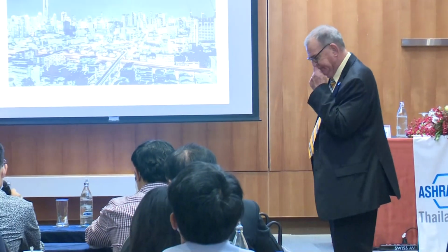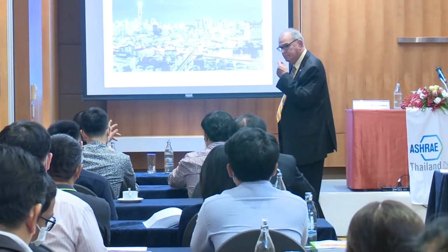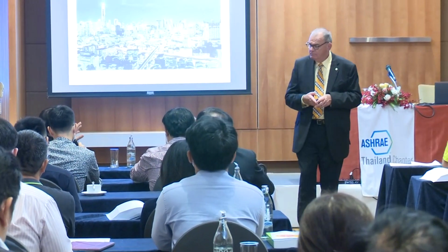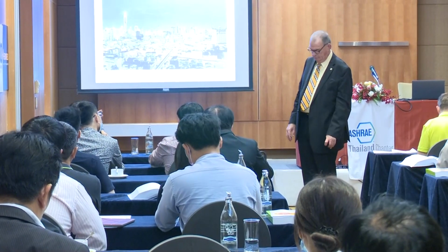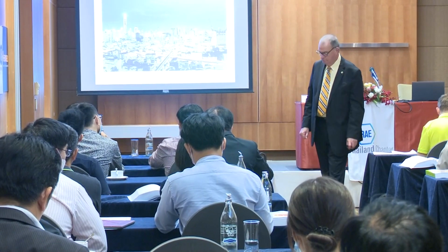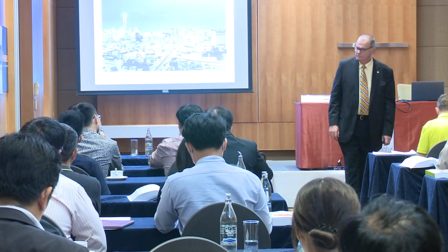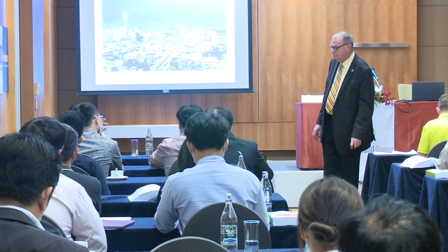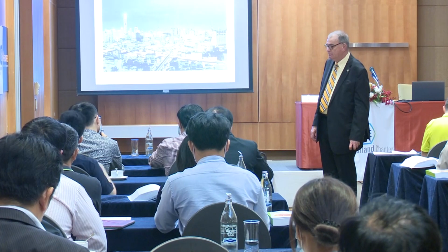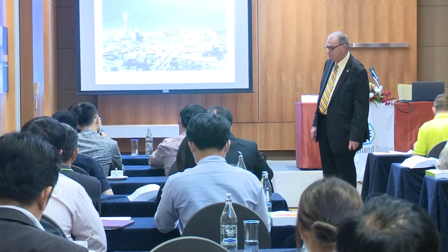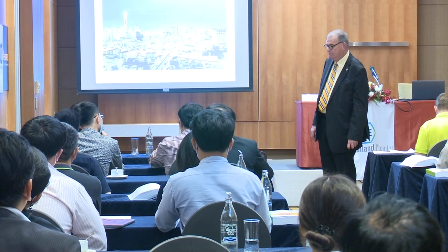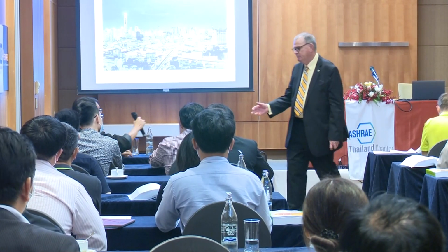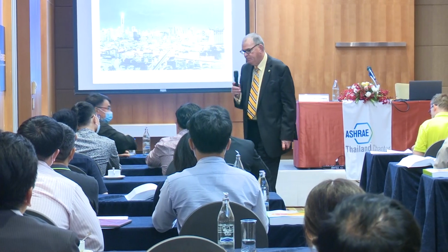I have a question because according to your presentation, the way you do the balancing is always touching the highest volume, right, for both air and the water side. Is there any other way to do the balancing apart from this? Because I heard some company from Australia, for the water side, sometimes they do backward balancing, not forward balancing. Also the air side, yeah.